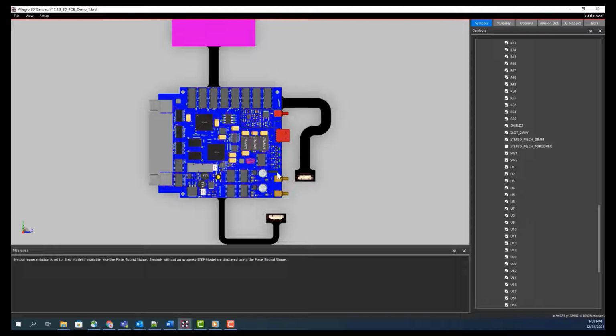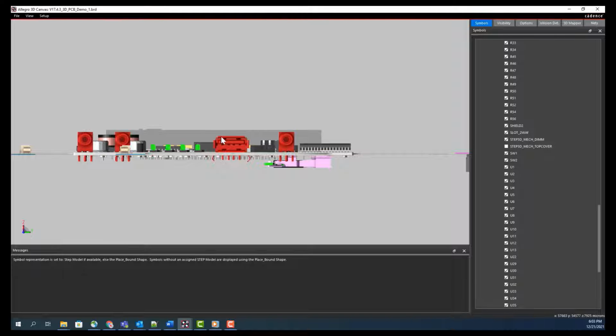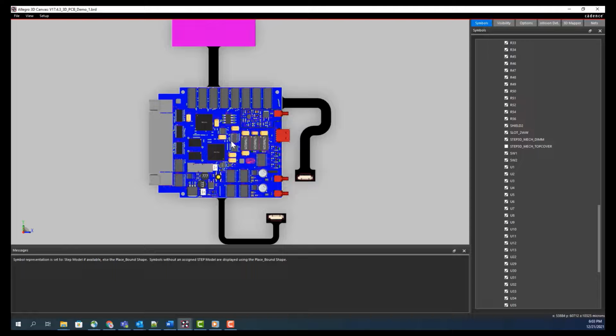I have selected some components here to confirm the side view. I have pressed numeric 6 to view the right side of the board and I scroll up to zoom in to see the clear picture. Again I am going to view the top of the board file by pressing numeric 8 and pressing numeric 7 to zoom fit the board.